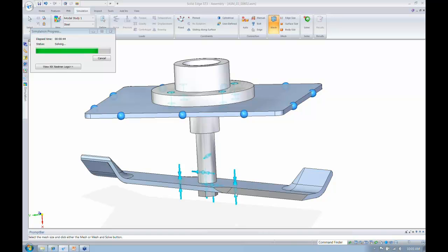Now forced vibration is when I have an input vibration to the system. Let's say I get a ding in this from where I hit a rock or whatever, or I have a grass buildup here, or it just was assembled a little bit off center. Anytime my center of mass is not at my center of rotation, I'm going to have a forced vibration input, and it's going to be at the frequency that this thing is rotating. For this chopper mower, it actually operates at about 3,600 RPM. If I divide by 60, I get 60 hertz. 60 hertz is going to be my input or operating frequency of this mower.